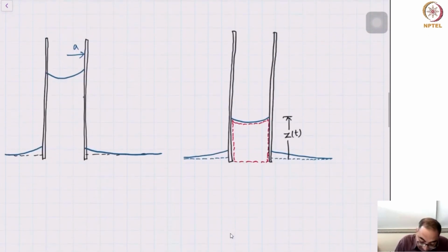Now let's say at any point we'll be making another important assumption, which is that the flow is fully developed. This is not true initially because of boundary layer effect, but once the flow has reached a fully developed state, then you can expect a parabolic velocity profile, and we can easily write down the velocity profile for this case, which is that the vertical velocity, if I call it u, is changing with the radius, where we are looking at a tube at any point r.